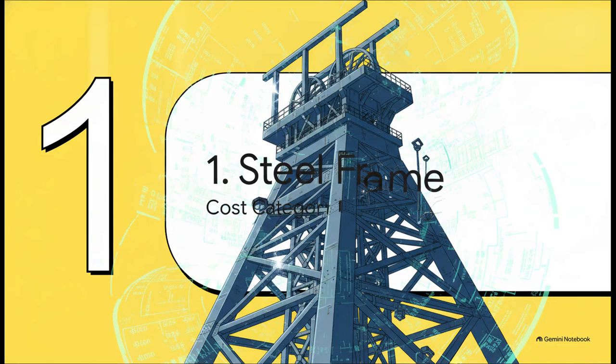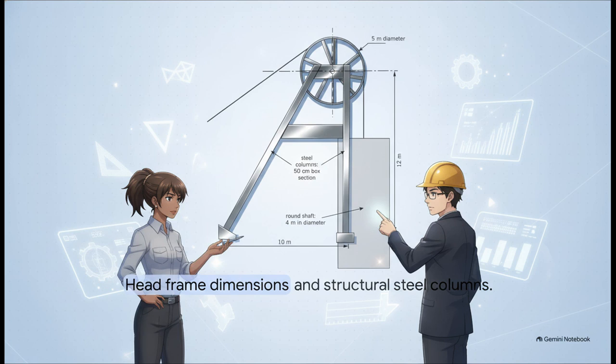All right, let's jump straight into Category 1, steel for the head frame. Now, when you're budgeting for your steel structure, keep in mind that your head frame has to be incredibly strong. We're talking serious rigidity, using triangulation to support that sheave wheel and handle the massive tension from the winch. But listen up, because here is the absolute golden rule for this section. You have to use the unique measurements from your own 2D working drawing. Seriously, don't just make up numbers. And whatever you do, do not copy an example. Your quantities are 100% based on your own specific design.